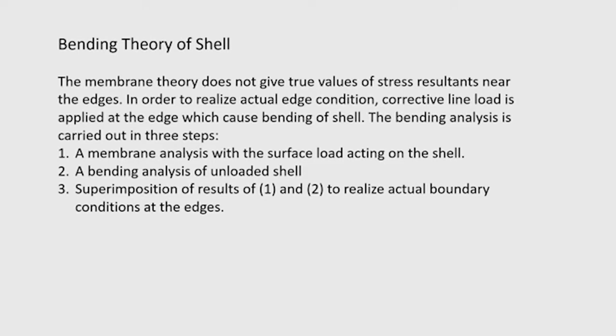Then we will do the bending analysis of the unloaded shell, because when we consider the bending moment in the shell, the order of the differential equation increases. Therefore, the characteristic equation will have a high order, that means it can go up to an 8th order equation. So, if we use the unloaded shell analysis, then we will find an equation of the wave, which will get damped out very quickly.